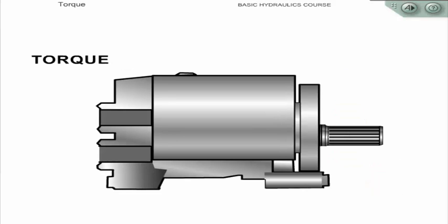This same theory applies to hydraulic motors. Hydraulic motors are actuators that are rated in specific torque values at a given pressure. The twisting force, or torque, is the generated work. A motor's RPM at a given torque specifies our energy usage, or horsepower requirement.